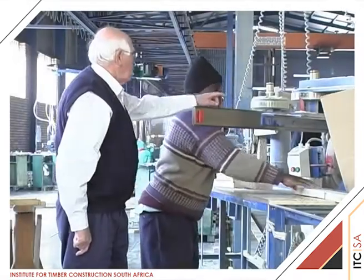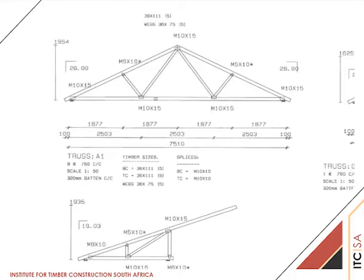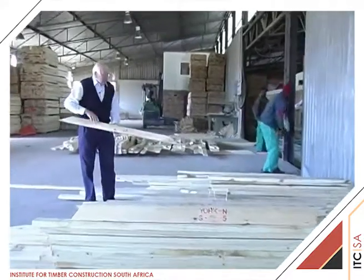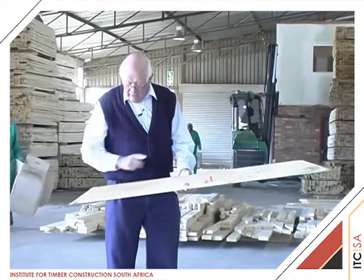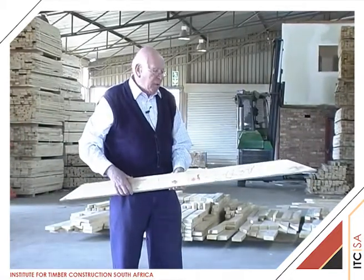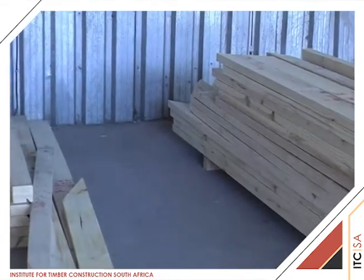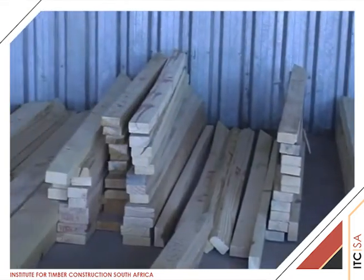The angle required according to the cutting bill is set, and then the operator will cut the length and the angle of the timber as required. These sections of timber have all been cut to length and to the angles which were indicated on the cutting bill by the designer. And all of these various pieces of timber would make up the components of the different roof trusses in a roof.